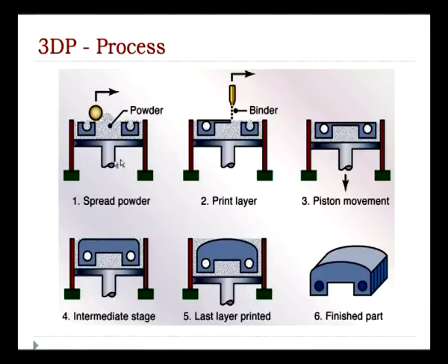Okay, first initially we start with a normal CAD file, along with STL file conversion, and finally we need to have the input as a layer, right? That is common for all AM processes. Here, initially we need to have a powder bed, right, which is going to act as a support as well as the product development area. This is the area where it is going to develop a product, as well as act as a supportive product development tool. So this is how the system is going to work.